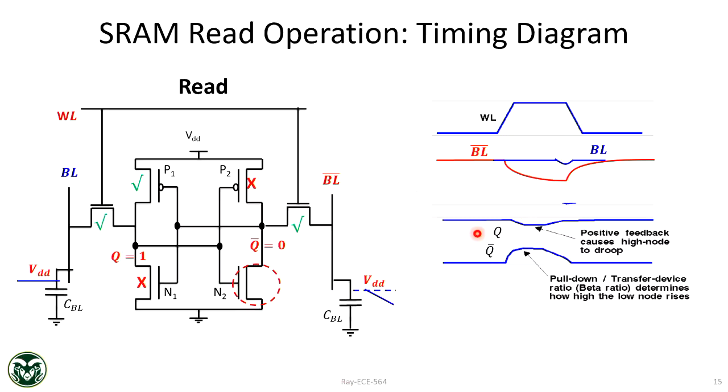Before the sense amplifier was invented, maybe in the 1980s, the SRAM was ultra slow. That's one of the reasons why the commercialization took place late, because in the absence of a sense amplifier, you have to wait so long for the bit line to discharge. But here, you don't need to wait. A little bit of difference created between bit line and bit line bar, you amplify it and latch it out. So that's the purpose of a sense amplifier. Because these bit lines are heavy.